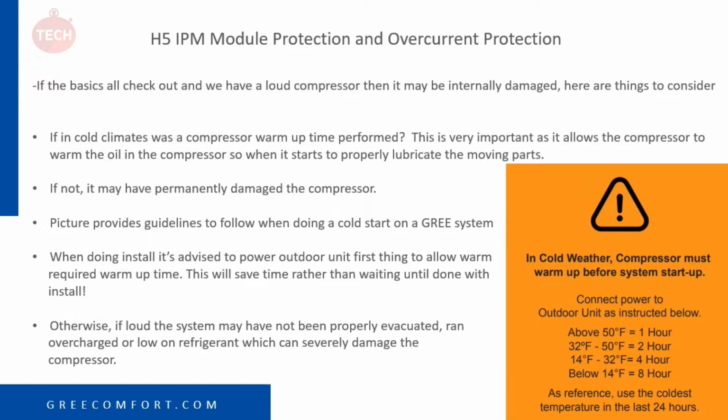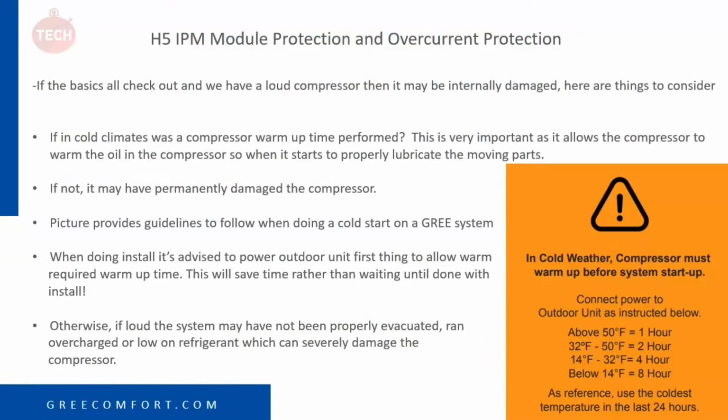Otherwise, if it's loud, the system may not have been properly evacuated, or ran overcharged, or low on refrigerant, which can severely damage the compressor as well. So if everything checks out, we went through the list, that compressor is still loud, and we didn't do a cold start on it, it may be something as simple as the unit ran overcharged, undercharged, or with a dirty condenser for a long period of time, and that caused damage to that compressor.